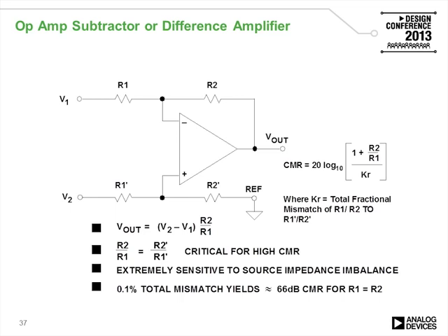If the matching of these resistors is not exactly the same, then the CMRR of this circuit is reduced. What this means is that the output will not be exactly the difference of V1 and V2, but will vary with the relative position of V1 and V2, the voltage of V1 and V2 referenced to ground.